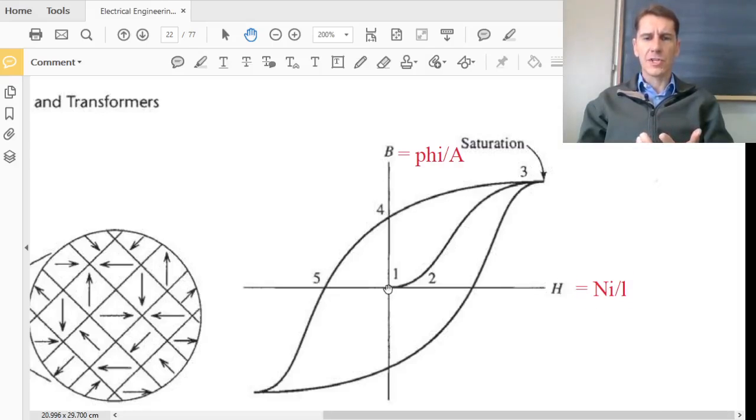So we put our H, our effort, in the opposite direction until we have enough domains looking in the opposite direction, so that my residual flux density is all gone, no magnetism left. Or if you've got your nail, if you start picking up stuff, eventually some of that energy stored in that magnetic field goes into whatever it is you're picking up, and it loses its magnetism. So that's the other way that you can do it.